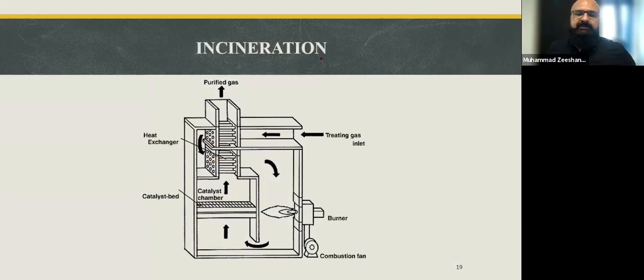The last option that we have for gaseous pollutants is incineration. Now, what exactly we mean by incineration? Means combustion, right? Literally, we burn the pollutants. And we burn the pollutants because combustion is an oxidation reaction. I hope we all can understand that combustion is a reaction in which the fuel reacts with oxygen and gets oxidized, right? There are pollutants which are less toxic in their oxidized form.